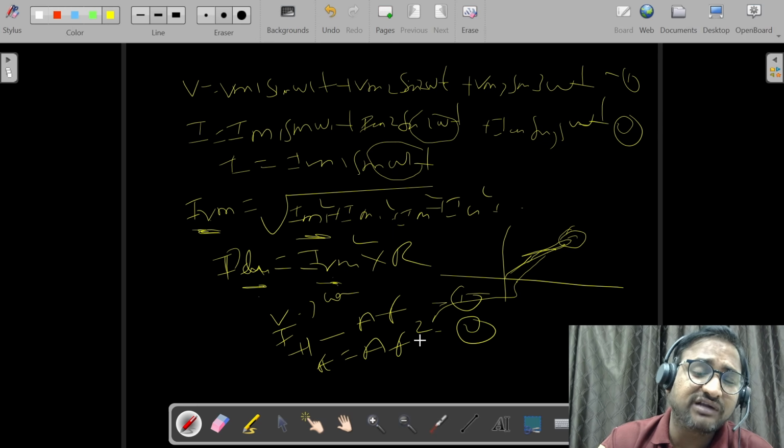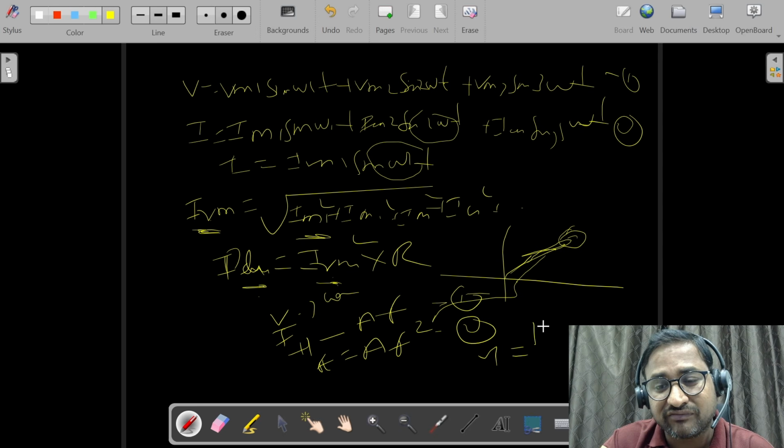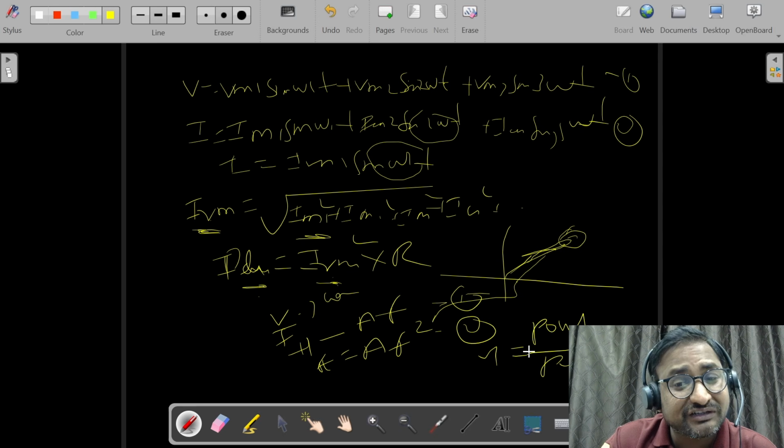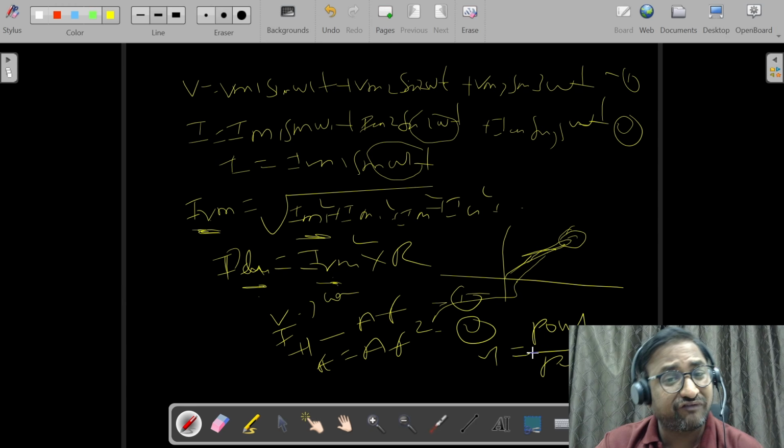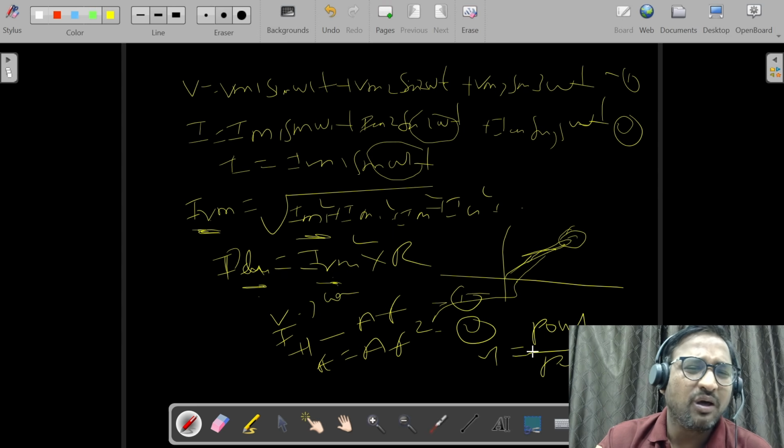If the losses increase, the heating effect will increase. If we give input Pin, due to more losses in the middle the output will be less, so the efficiency, which is given by Pout by Pin, will also decrease. These are all the effects of harmonics. Once harmonics come into the system, the IRMS square increases, which means the current will increase in the system.